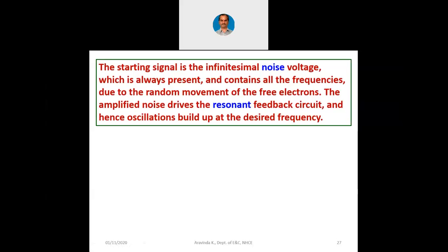Now to prevent the distortion, we have these measures here. Otherwise you may think it will keep on infinitely getting amplified and the sine wave may become a square wave, with the transistor switching on and off between cutoff and saturation if it is a BJT. You may think that way. No, it does not happen because we have some other mechanism to prevent the transistor going into cutoff and saturation. That I will tell you later on.